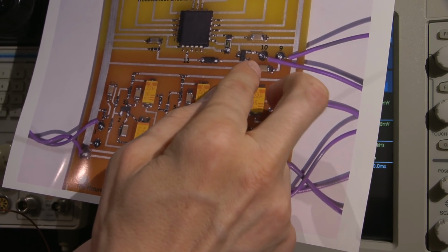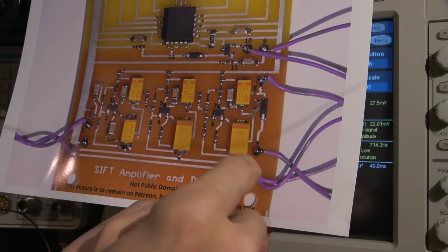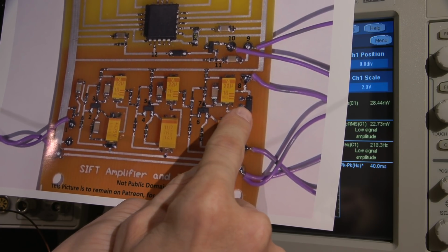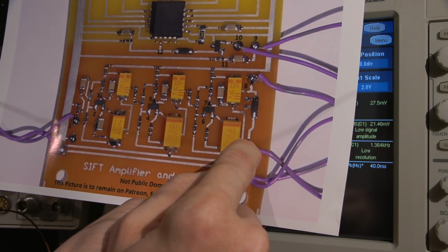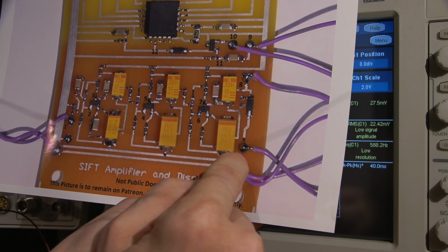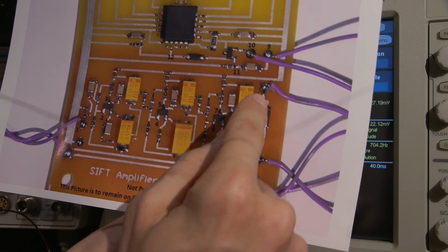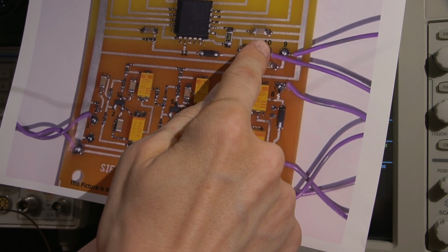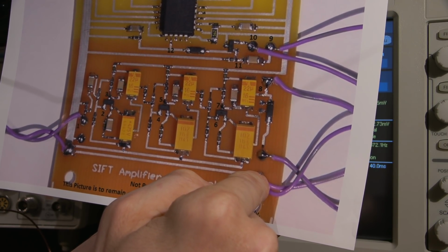So we can route the signal to either this point or to this point. And in one of the positions, this diode is connected, and in another position, this is open. If we do a little bit of further research and very carefully trace those wires on the schematic, we'll find that in the gain position, which means that the signal is going to be coming out at number 10 here, this diode is open. So this is open here.